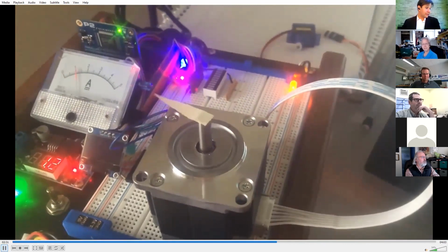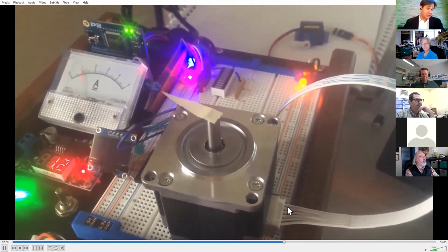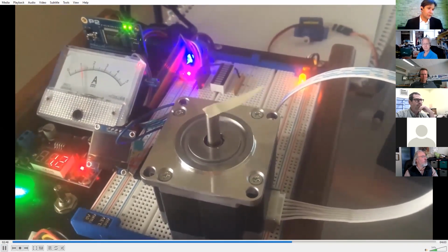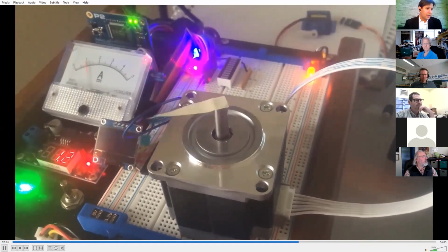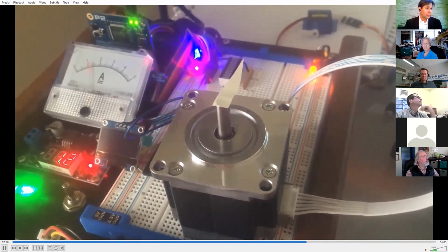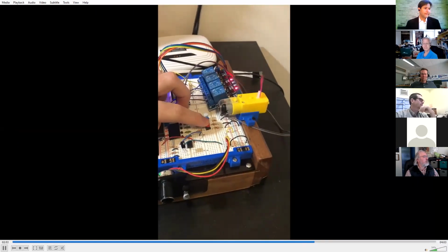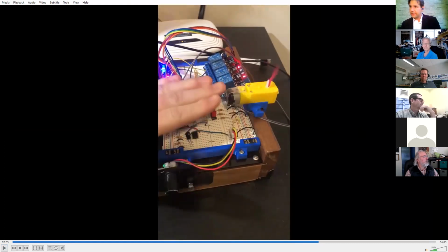So I'm teaching them how to program stepper motors. We use 6 lead steppers because then we can use them as unipolar stepper motors and just have them run through a Darlington transistor array with the current going in one direction. But then, as another project at the end, we used a bipolar stepper motor mode. We just used 4 wires and we were able to use a microstepper driver chip. This last one is an exam that I had them do. I'll talk about that in a second.